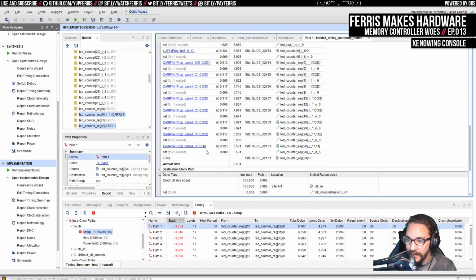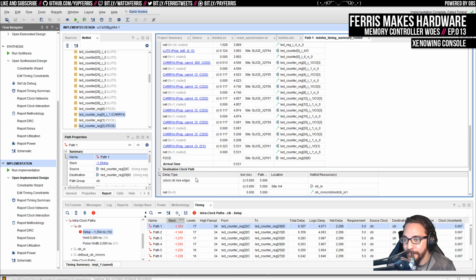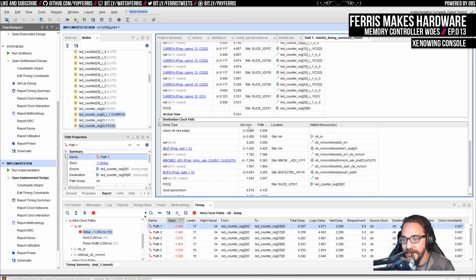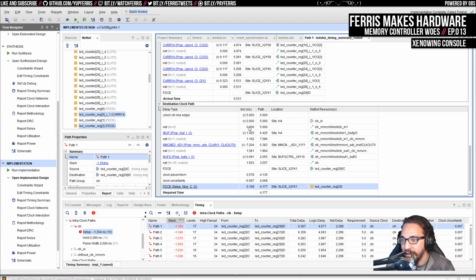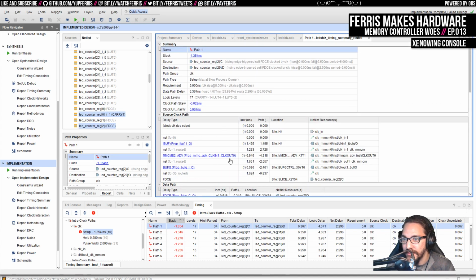I think, again, that's because the way I wrote this logic, we need to know the result of that addition and the result of that compare before we can know what the value for this bit is going to be. Yeah, that's what this is. The C is the clear. It's the clear in the data, because the clear input is based on the data output. We don't know if we're going to clear until we've calculated the addition and the other thing. So we see the path there.